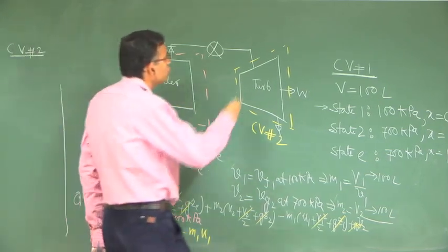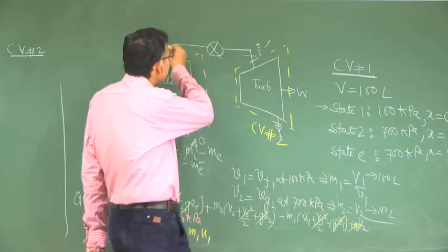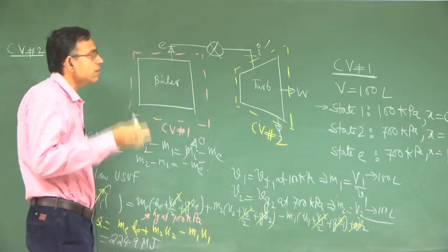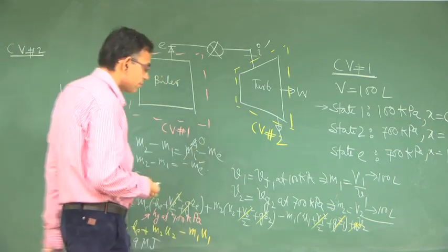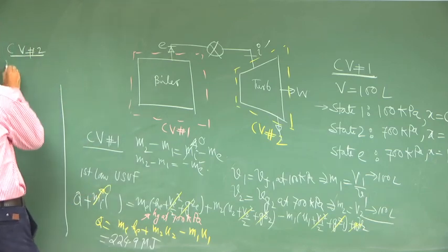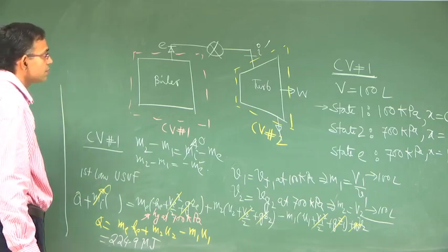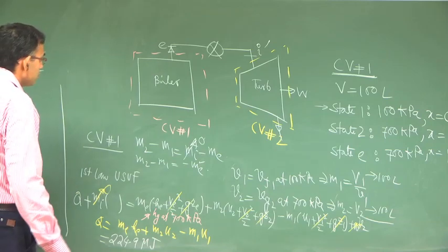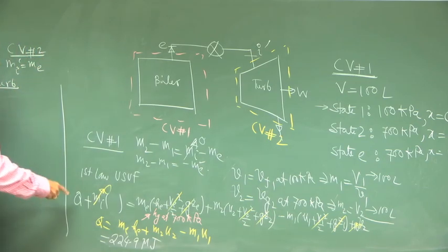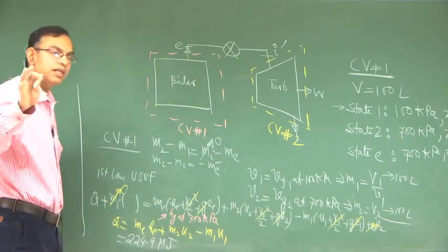For control volume 2, let I prime be the new inlet state, which is the same as E, at least for enthalpy, not for everything else, but we require only the enthalpy. So, mi prime will be equal to me, right. For the turbine, let us write this general law, which you can apply for steady, unsteady, whatever.